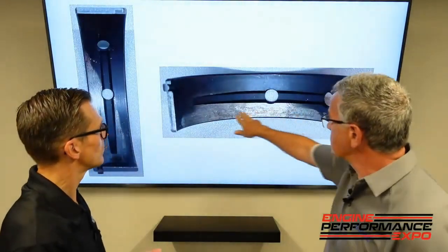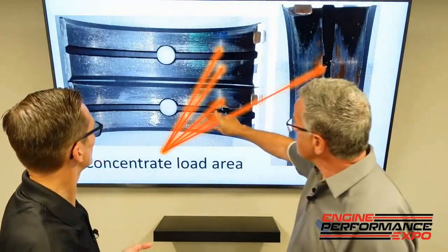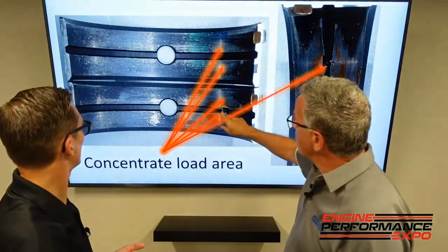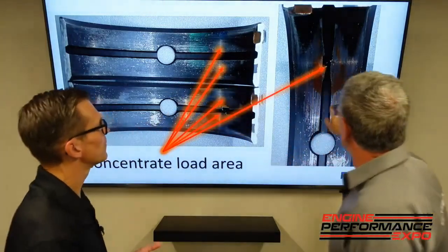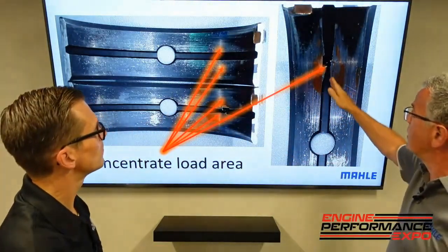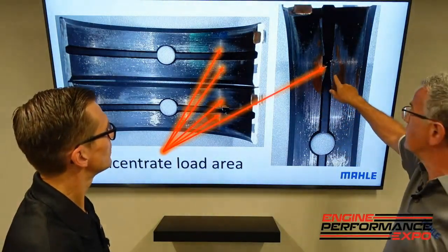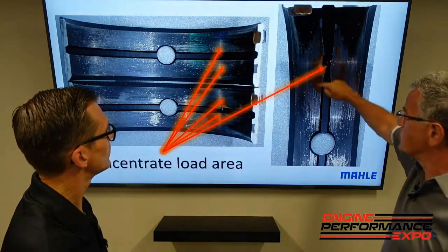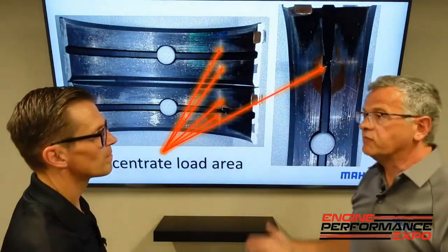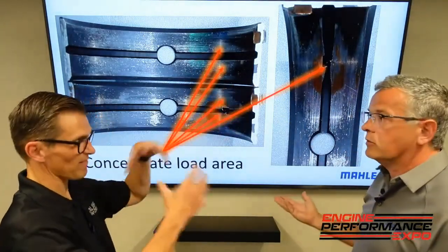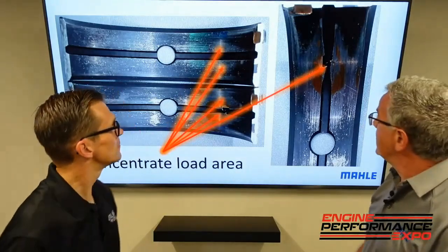In this case, you can see the bearing is wearing here. There's so much wear on this bearing that the copper is showing, again uppers. These are uppers. Yeah. All right. There's a higher view of it right here where the crankshaft is hitting so hard here in the fatigue that the copper is showing in here. But as you can see in the other areas, the bearings still look relatively good. Yeah, it's just in that area is where that flex is, and it's just killing the oil film there. Yes. Locally. Yep. In an upper.